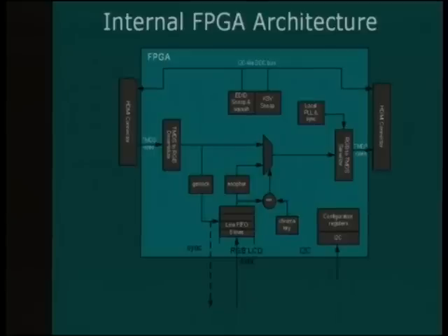At the end of the day, this is what it looks like on the inside of the FPGA. There's a FIFO that takes the video coming in, line by line. We encipher it. We have a multiplexer that picks the pixels, a chroma key detector, and then the man-in-the-middle mechanism up top.